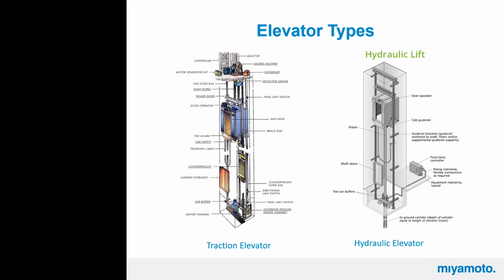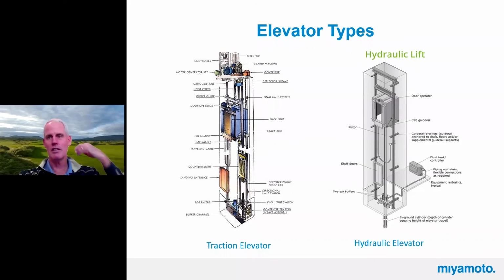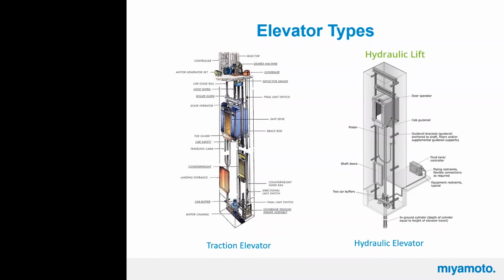Thank you. Oh, thanks for the question. We've only had problems for the elevator override when we go above the roof of the building for wood buildings. Then it becomes a little tricky to support the guide rail support. Other than that, there's some coordination issues, but the steel to wood kind of works out. And I think Jeff probably had a difficult elevator to deal with at the time for that building.